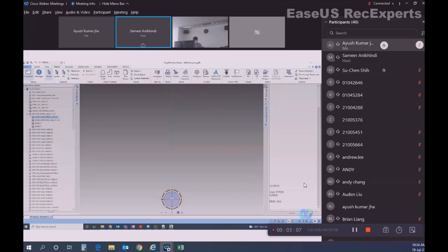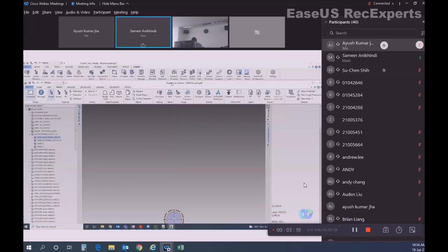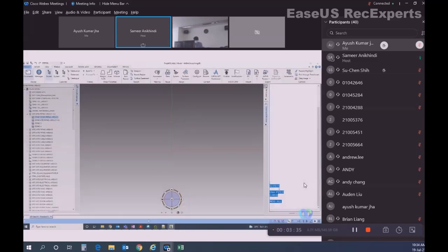At the top, you can see it gives information of the current project, project APS, the MDB all, and the current module. Module is model, everything 3D. So similarly here, you can see it gives information. But to check the current user, you have to use this command, Q USER, Q MDB.